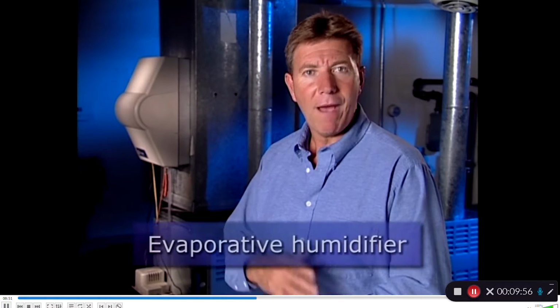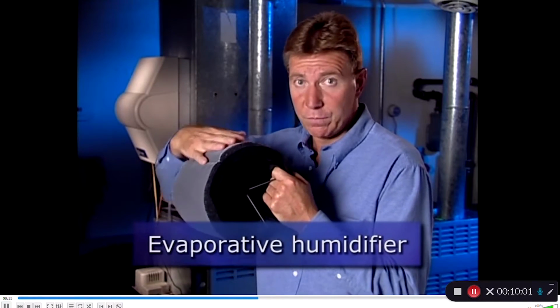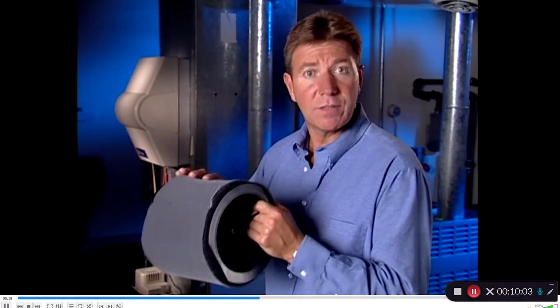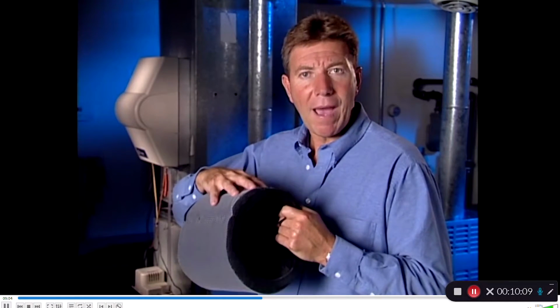Because the relative humidity of the air in an occupied space is low in the cooler months, mechanical devices called humidifiers are often incorporated into the forced air system to add moisture to the air. Evaporative humidifiers work on the principle of providing moisture on a surface called a media and exposing it to the dry air. Since the air is drier than the wet surface of the media, moisture evaporates from the media and is introduced to the air in the duct system.